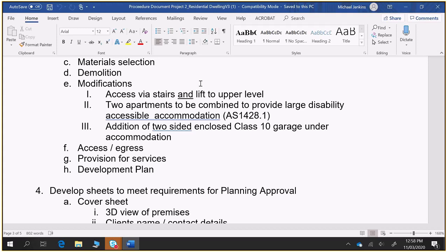So what I would start with, I'd start with my driveway access and my car park layout at the bottom. I'd make sure those things work whilst keeping in mind that I'll have some staircases there. Then design my staircases and make sure that that interaction between the car parking and the staircases works suitably, and there's sufficient space for navigation of disabled people upstairs. And then once you've got those big picture bits in place, then the rest is quite a bit simpler.